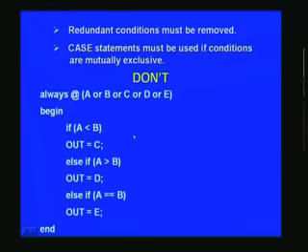This is another case where redundant conditions appear, and you will have to remove that. You have to identify where the redundant case is and remove that. There, what is redundant? We will have a look at this, and don't follow this type of coding, right. If you do, you will create an additional mux and hence additional delay, and that in turn will slow down your frequency of operation. And how it does, let us see.